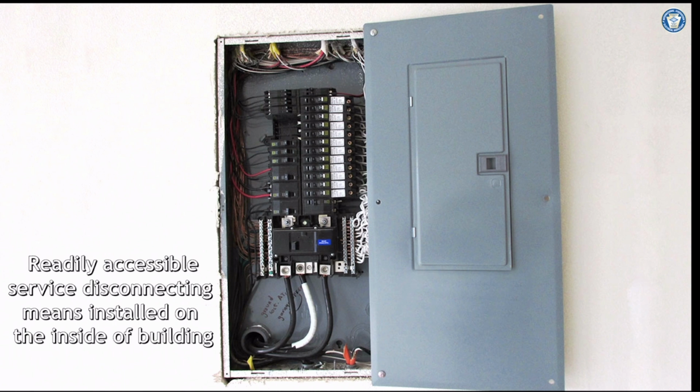This is at the point of nearest, right? Because of the rules. So it's got to be the nearest point of entry. And then you have your service conductors down there on the bottom. So this is a bottom fed panel board. Those are your service conductors. Your grounding electrode conductor should be in there too as well. So all of that, and then all of your proper bonding.